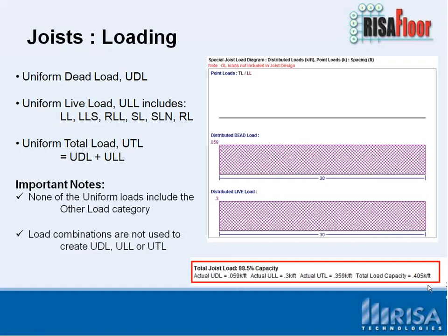One thing that's important to note is that none of these uniform loads include the other load category. So we have dead load and live load, and there's other categories available to you called other load, and that won't fit into these uniform dead loads and live loads. So we do put a nice note on the top of the screen, OL loads not included in joist design, so you know that going right off the bat.